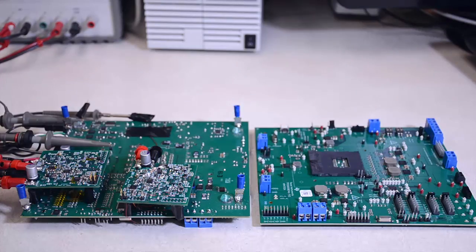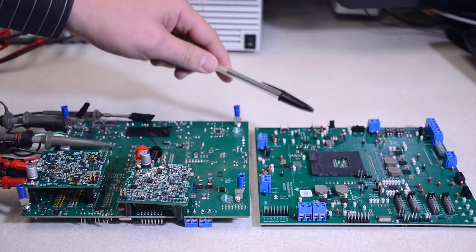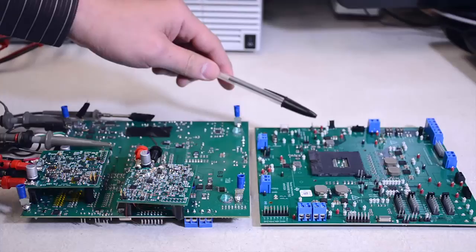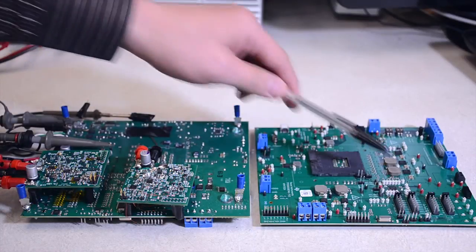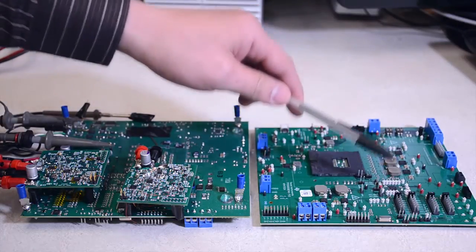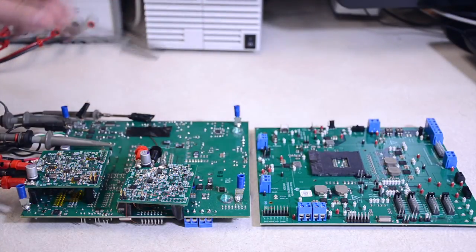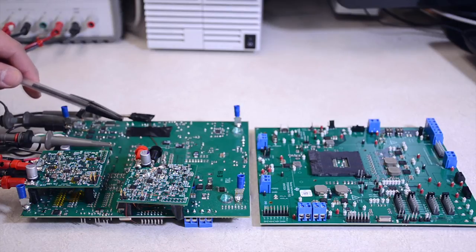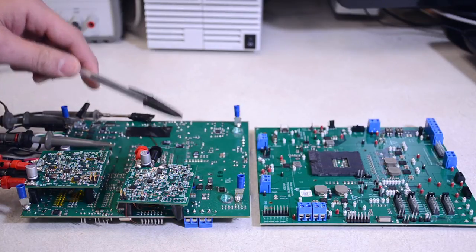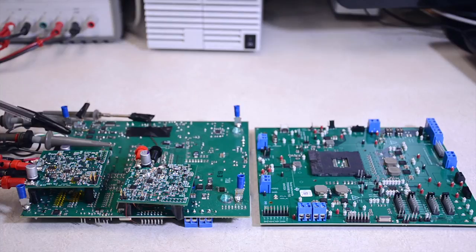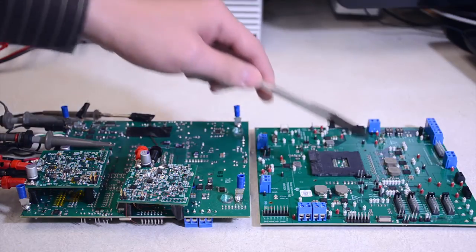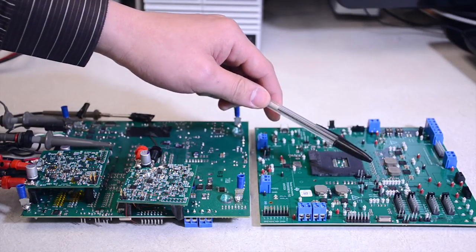Here is the experimental platform. The top side PCB contains a 4-phase buck converter, 2 phases in here, another 2 phases in here. Also, there's a controller from Texas Instruments. The bottom side of the PCB connects to 2 daughter boards, and these 2 daughter boards are used to implement the adaptive PLL loop circuitry. The 2 PLL loops will work with the 2 phase managers inside the control chip to construct the 4-phase hybrid interleaving.